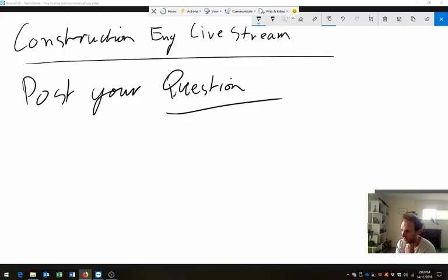Okay, thanks for the question. Hopefully you can hear me. So the difference between shallow basements in clay material and shallow basements in sandy material. The latter is not suitable for deep well dewatering. However, I think deep well dewatering is suitable to moderate to high permeability soil from the lecture.